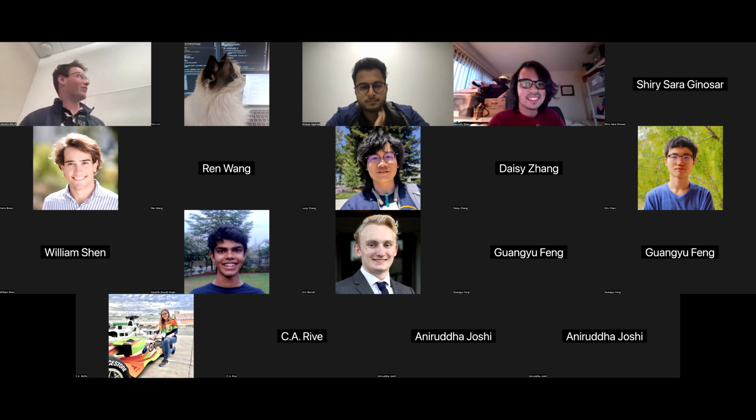Yeah. What are your thoughts on force sensing, like proprioception within the joint itself? Yeah, so Ananya obviously showed with Sim-to-Real that the proprioception is definitely very useful. And of course, this is one of the issues with tendon-driven designs, you lose some of that sensing. I think proprioception will be useful for a while. Honestly, if you have it, you should use it.